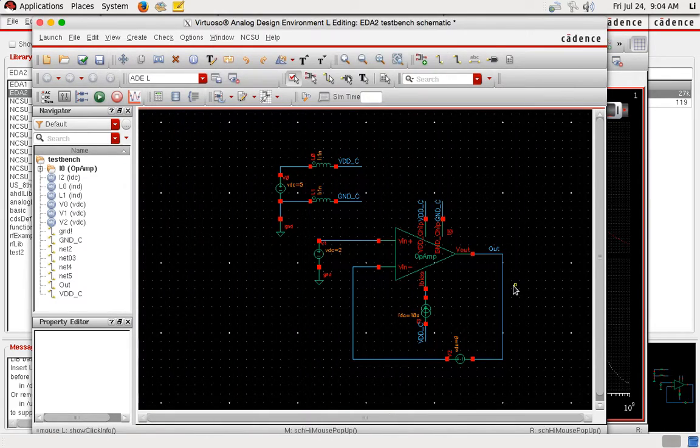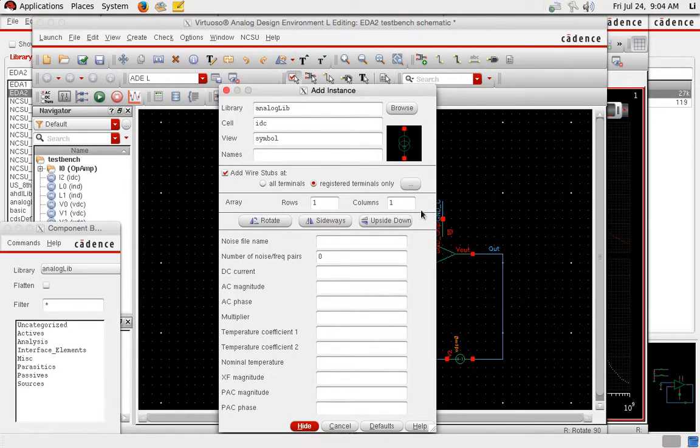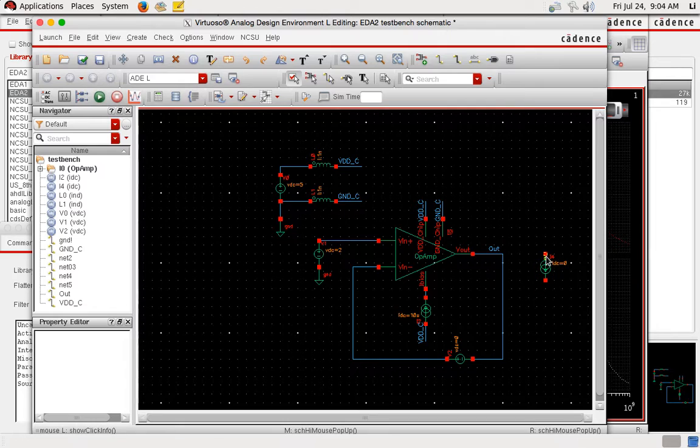Okay. So go back to the schematic. I'm going to add a probe. As I said, this is a counterpart. So instead of using voltage source for stability simulation, for XF, I'm going to use a current source. Okay, and this current source, I'm going to make sure the DC current is 0 amp. If I have 0 amp of current placed here, it's never going to mess up with my DC operating point, right? That's a nice property.